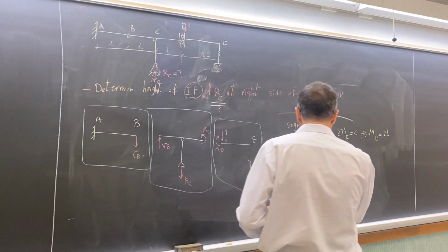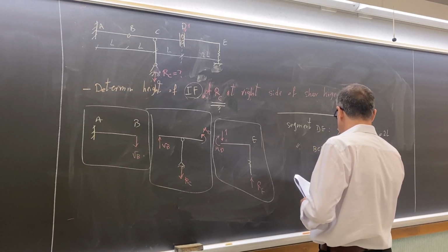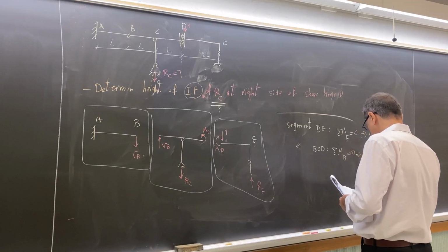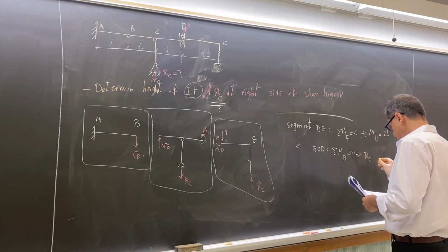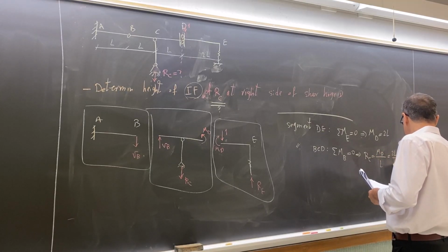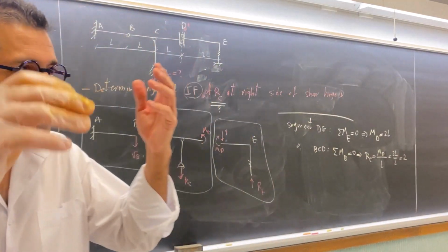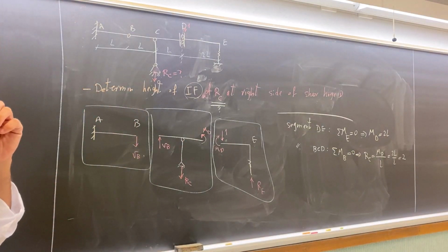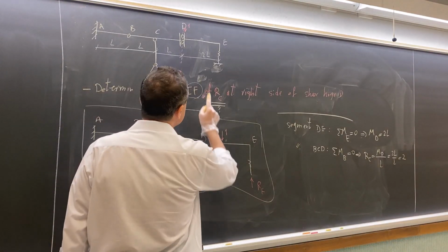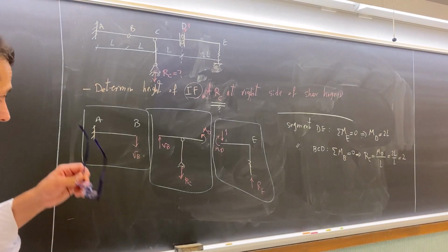And then when it comes to segment BCD, we take a moment about point B. From here, RC is MD divided by L, which is 2L divided by L, which is 2. We don't use unit. The unit could be Newton meter, etc. So the bending moment at point D, which is the shear hinge, is 2. For example, 2 Newton meter. So we have a bending moment.